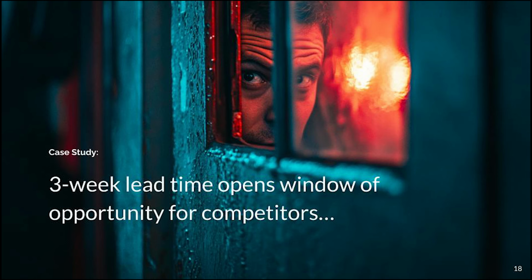Some of the things we did was we identified the bottlenecks in the process. We established a cellular flow, so we made the flow of the product work in a much smoother fashion. And just using some of these concepts that were covered, we decreased our lead time from 3 weeks to 2 days. So that's an 87% improvement. And that's without hiring additional people. And these are some of the low cost, high value wins that you can get by looking at processes in a different way, by understanding where your bottleneck is and how it is affecting your operation.